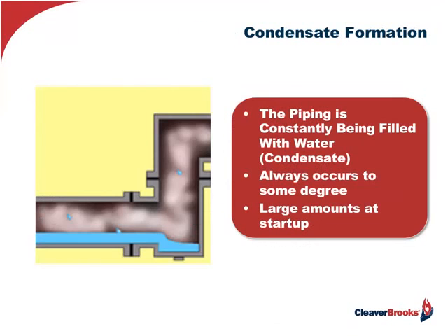Now, talking about velocity and talking about these pipes that are radiating heat, the steam distribution piping, you're going to be generating a certain amount of condensate, obviously. And depending upon the amount of insulation you have on the piping, it could be even more. Less insulation, no insulation, a lot more liquid's going to accumulate as far as condensate in that piping. And notice also the 90-degree bend here that I'm showing you. So, this is probably normal operation.